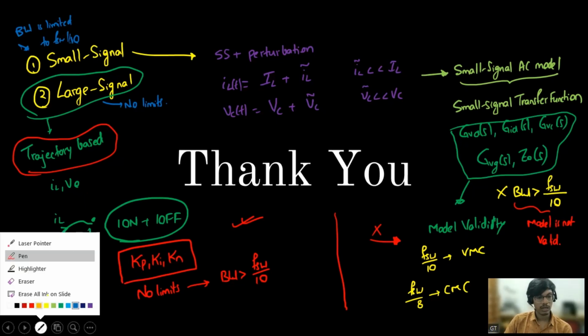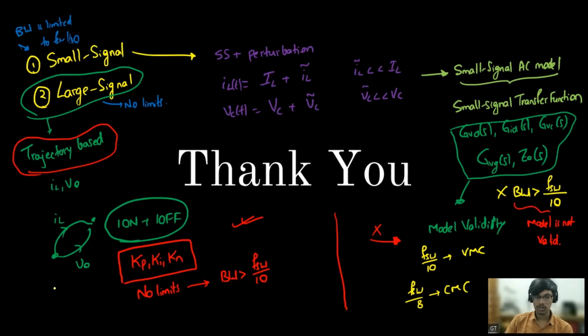Now the question is why we are learning small signal, because large signal tuning is not quite simple and it is somewhat complex compared to the small signal. So when we actually start with a controller, we first want the converter to operate in closed loop, and first we are not bothered about the response. First we want to operate under closed loop with some gains. But how will I know the gains? So first we'll do the small signal analysis, so that it will give me some estimation of controller gains, and I can operate with this even though it is limited to 1/10 of the switching frequency.